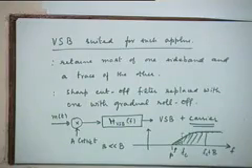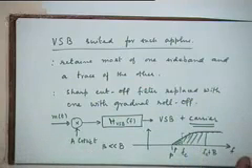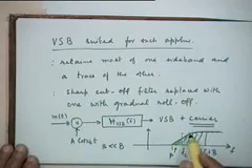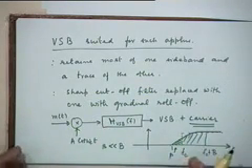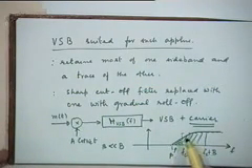Well, the answer to that question is what we will now try to obtain, and we will find that the principle is fine, but you have to be careful in the design of this filter, if you want a demodulated signal which is proportional to m(t), a replica of your message signal. So that's what you will like to understand. How should such a filter be designed? I'm not getting into filter design. I'm getting into what should be the nature of the transfer function of such a filter, such that we are able to reconstruct our message signal back, because that's the ultimate requirement.